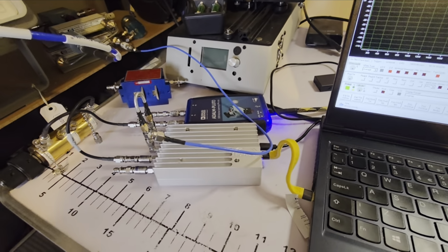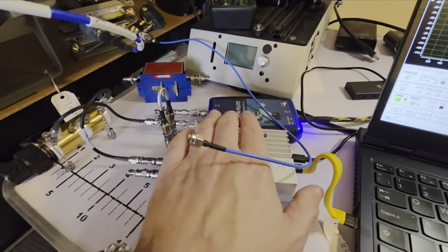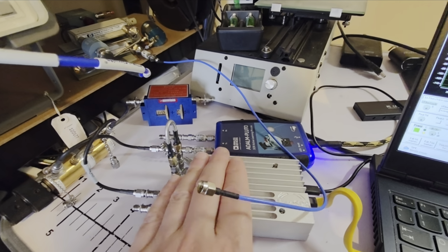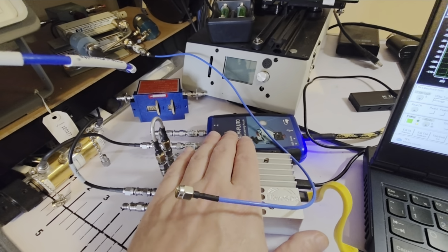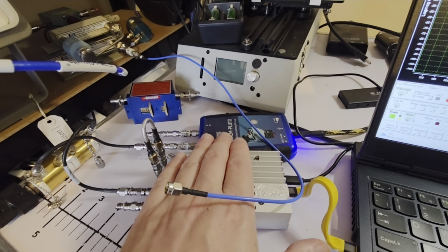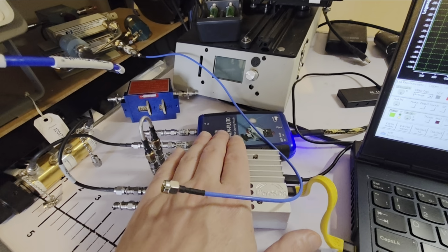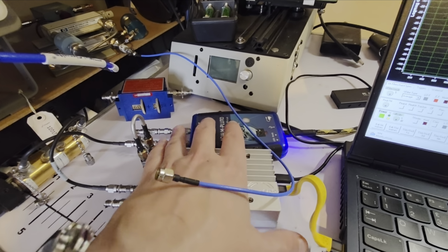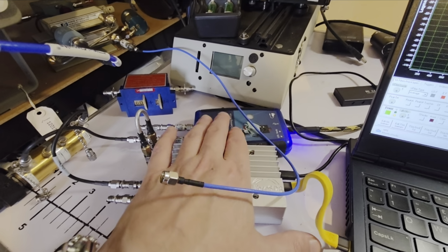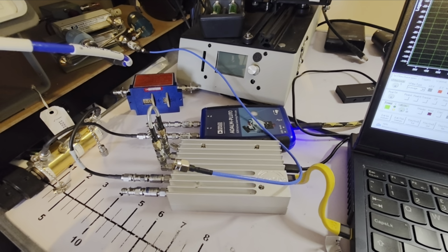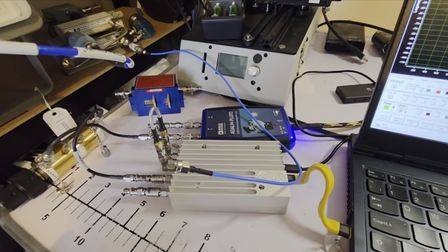And you can do it with one device like this. With one device you cannot do VNA, but you can do the rest: spectrum analyzer, tracking generator, and generator up to 6 gigahertz. But with one, because there is internal crosstalk, the dynamic range falls quite a lot.